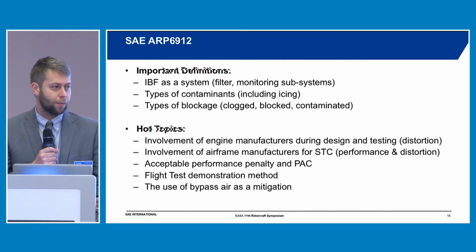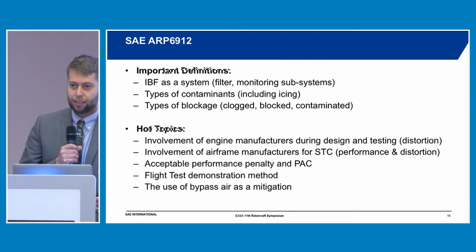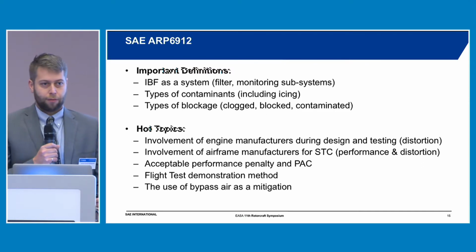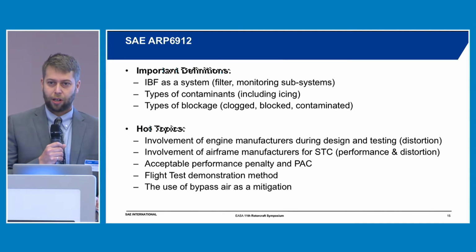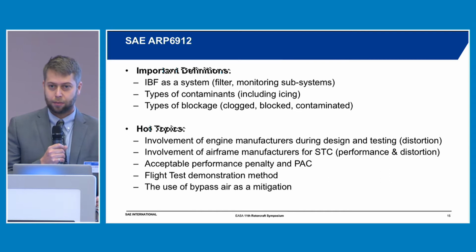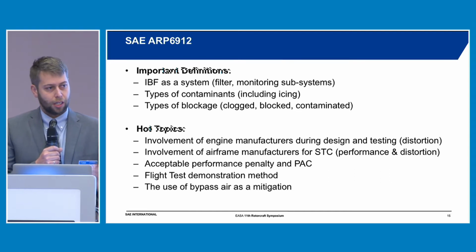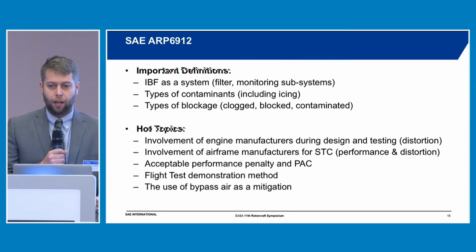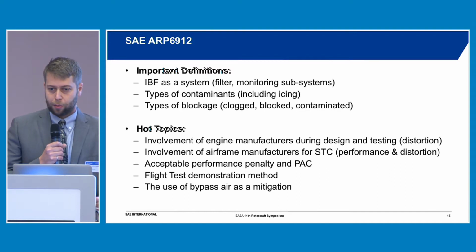It will look at the IBF as a system. Right now, a lot of the STCs and even the installation during TC look only at the filter itself. It's not recognized that the IBF is actually a system, including subsystems. Not just the filter, but also the sensors, bypass door if there's one, and the human-machine interface.